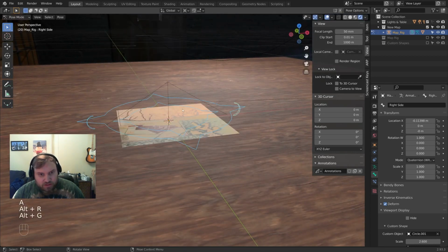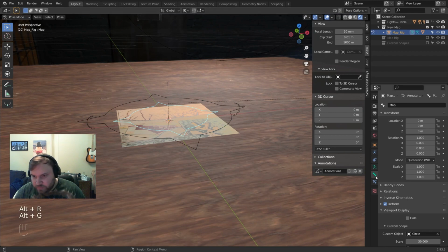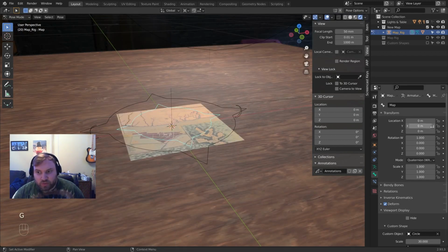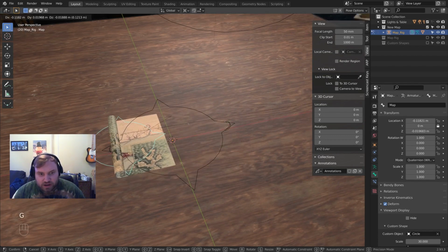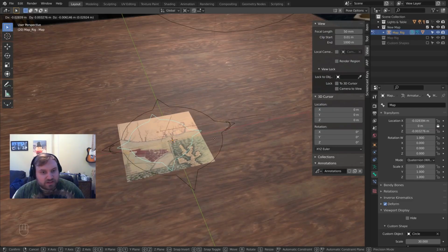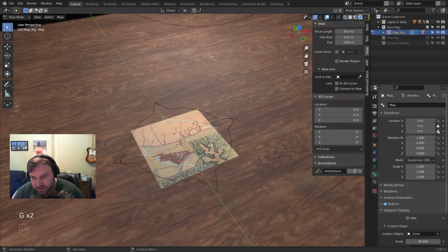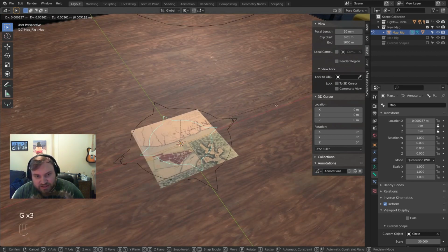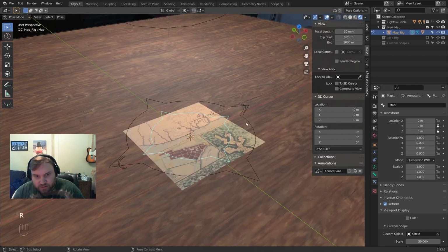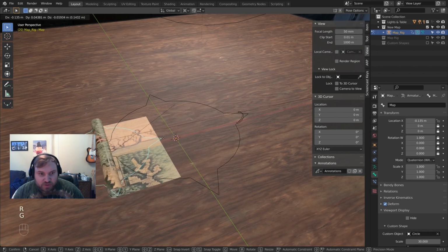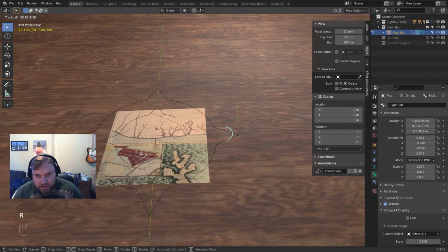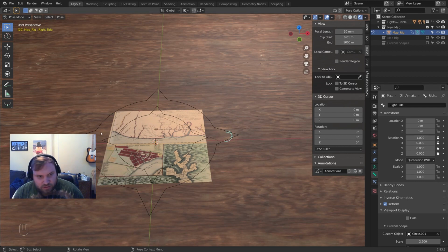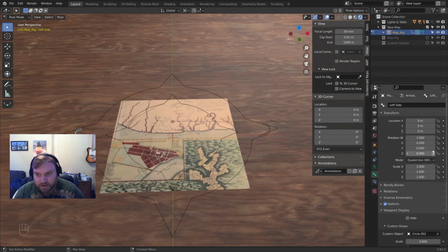So we'll just start locking things that shouldn't move. If I move this upward, it's actually the y-axis I have to lock. Since that's locked, if I move this around, this is perfect. I can move this around as needed. We're going to lock the Z as well, so it just moves on the x-axis if I grab it. This guy needs no rotation, so it can't move at all. The only way I can move this is left and right. This one, same thing. I don't want any rotations, it looks like, probably for either the left or the right side.